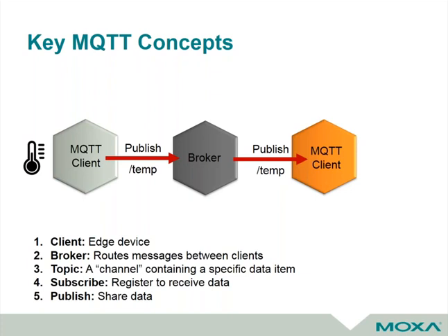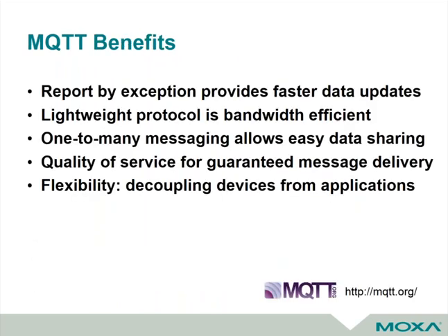The client on the left has said, hey, temperature has increased by, let's say, 1%, that's determined by the client. That client can then publish that to the broker, and the broker takes the role of distributing that to all the clients. We've done a real simple example here, but I think you get the idea of some of the different architecture of this type of system as opposed to those more conventional SCADA applications with polling. And there's a lot of really interesting benefits to this when we look at how that works in an overall system.